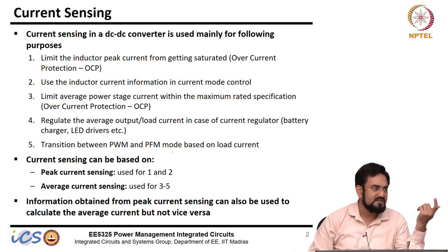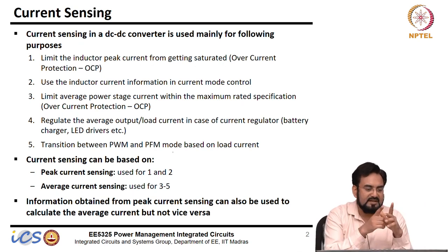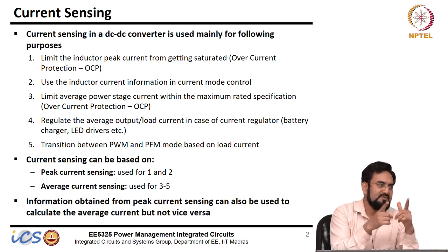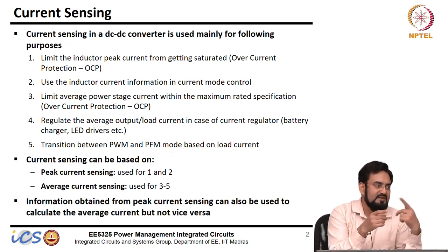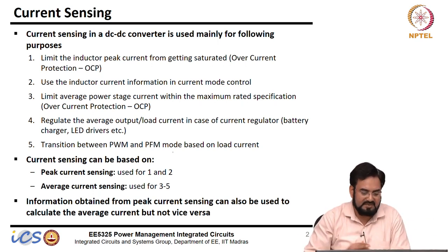You know the control voltage. If it's voltage mode, you know at what control voltage you get 10% duty cycle, or you can literally measure the time with a high frequency clock. You can count that pulse width, and you know that this 10% duty cycle is this pulse width, and the high frequency clock will count 10 or 20, whatever, and that count you can implement digitally.